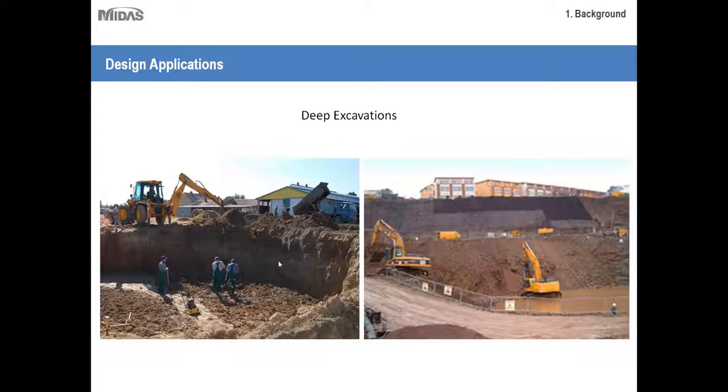So if you look to the left here, the shallow excavation, there isn't really much of a slope at all. It's almost a 90-degree angle. So why is that? The reason is just that the excavation is so shallow that the slope is negligible. You could still have a 90-degree angle such as this, and it would still be relatively safe to walk along the perimeter here. You don't really have to worry about it failing.